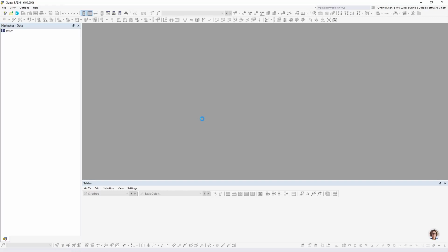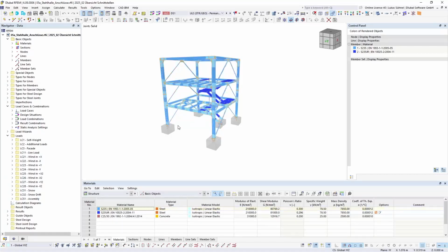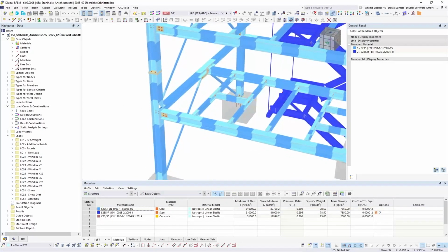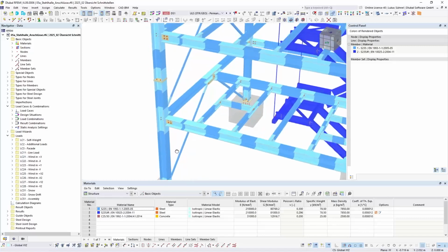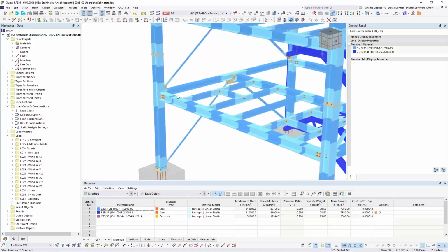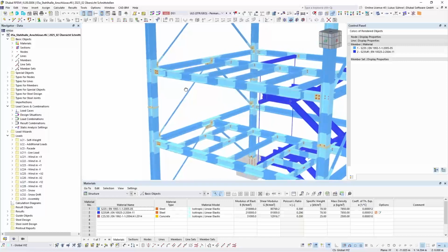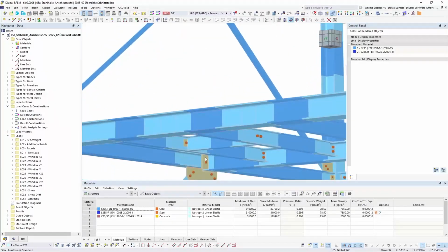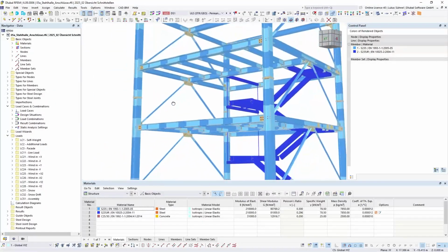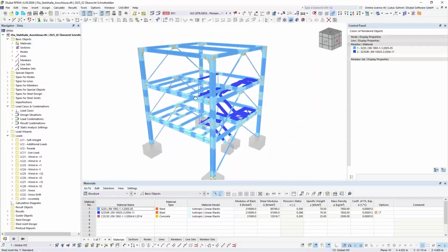The benefit is that it's possible to design 3D joints. So there's basically no limit regarding the number of members that are connected to a joint. The members can come from any direction. And it's also not limited to specific internal forces, so any force that you have in the internal beams can be considered. This is the new steel design add-on. You can see here every joint has been designed, and that is quite a nice graphical representation that we have here.